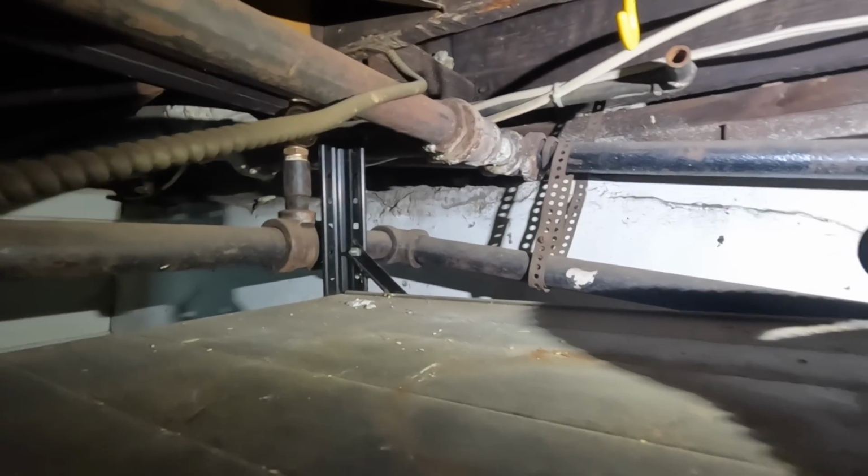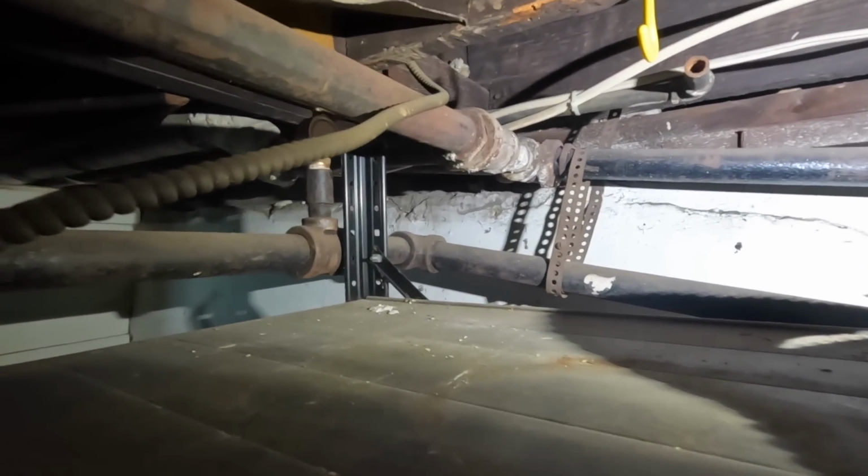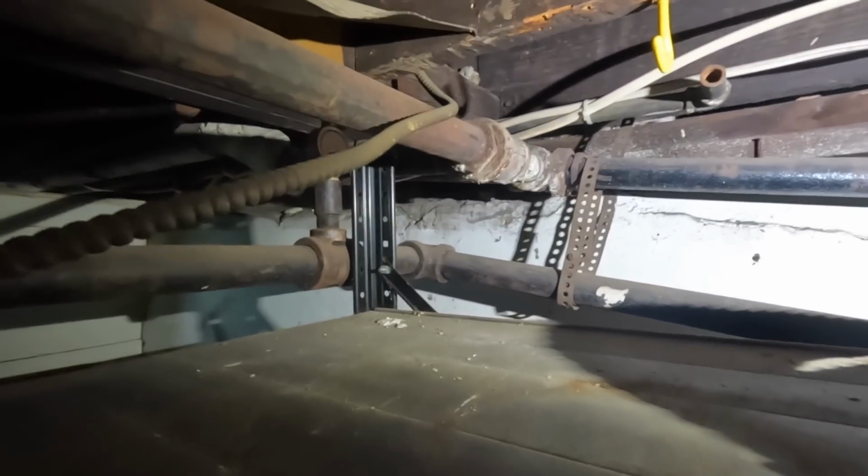I turn on everything in the house that I can: lamps, lights, check receptacles, whatever I've got to do. And then I turn off the circuits that I know are connected to knob and tube. Then I go throughout the house to see what's working and what's not working. And whatever's not working needs to be addressed individually, one at a time.